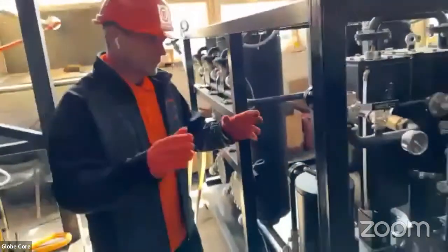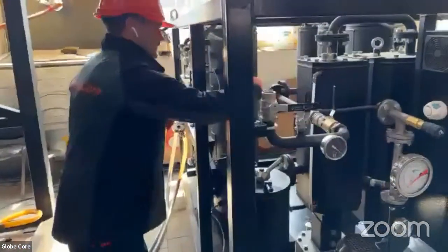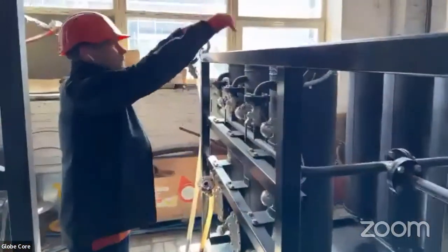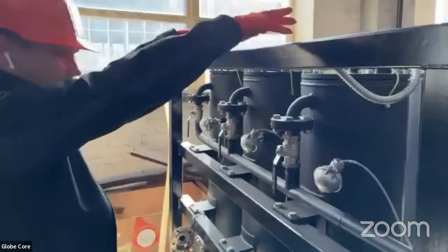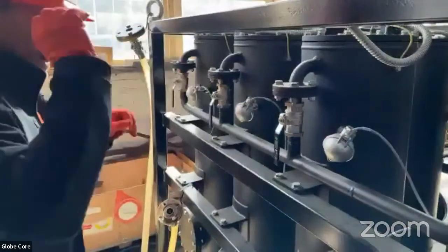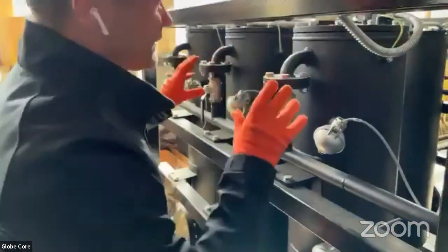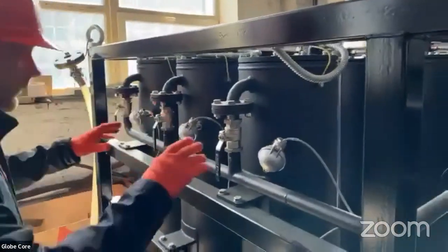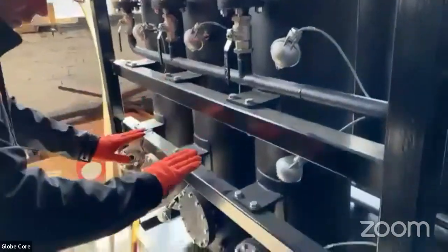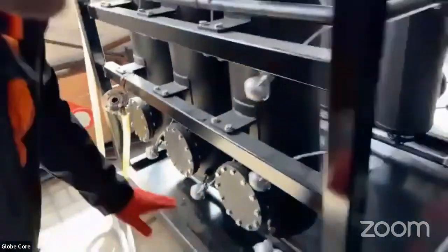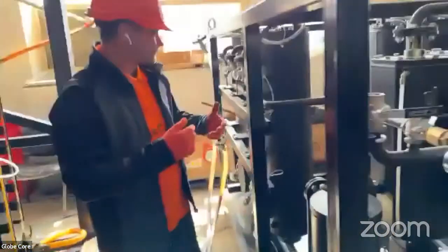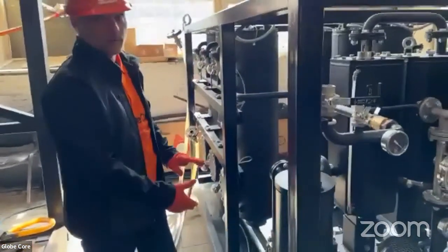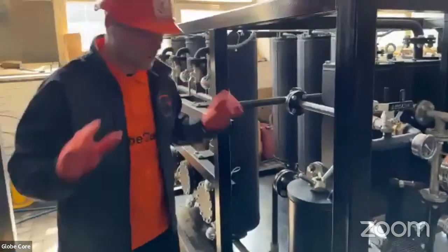So air, due to operation of the vacuum pump, goes into this line, into these wings in parallel. Then the sorbent is ignited from the top. After 60 to 80 minutes of operation, heating elements go off. The burning process goes by itself. And when the burning layer goes through all the volume of the sorbent, the reactivation process is over.